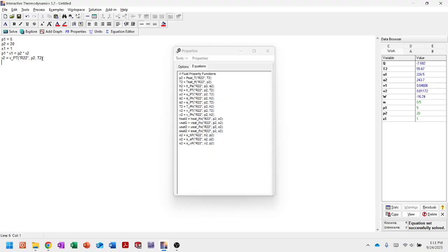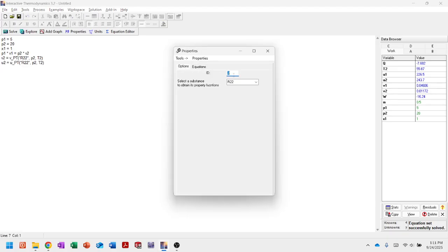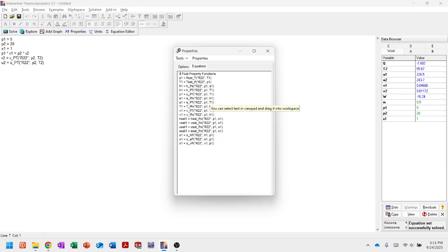Now we can find U2. Oh, I didn't need to write that out. U2 is a function of pressure and temperature. So grab that equation. We also needed U1, which I should have gone back to. There's U1. I'm not going to grab the whole thing, I'm just going to grab USAT of this. There we go. We have U1, U2, V1, V2. I think we're pretty close there.